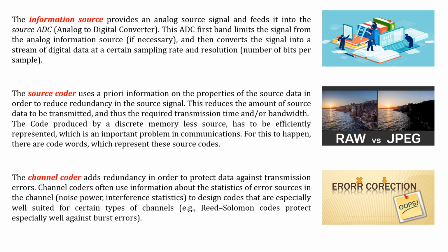And then later you have the third block, which is the channel coder, where this block will add certain redundancy information. This block adds information that is responsible for error correction and error detection. As you know, the signal will be sent over a noisy channel, so my data will get affected because of lots of factors, such as attenuation, fading and so on.